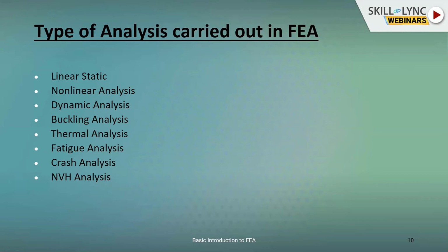The types of analysis which we generally carry out are linear analysis, nonlinear analysis, dynamic analysis, buckling analysis, thermal analysis, fatigue analysis, crash analysis, and NVH analysis. I would like to give a brief summary of each of these. In linear static analysis, we consider that the load we apply is constant throughout time; it is not varying with respect to time. If you plot force versus displacement, it is a linear graph, with a linear relation between them.